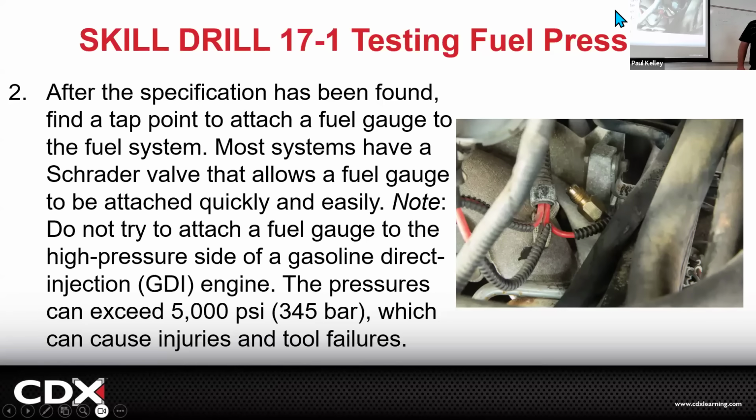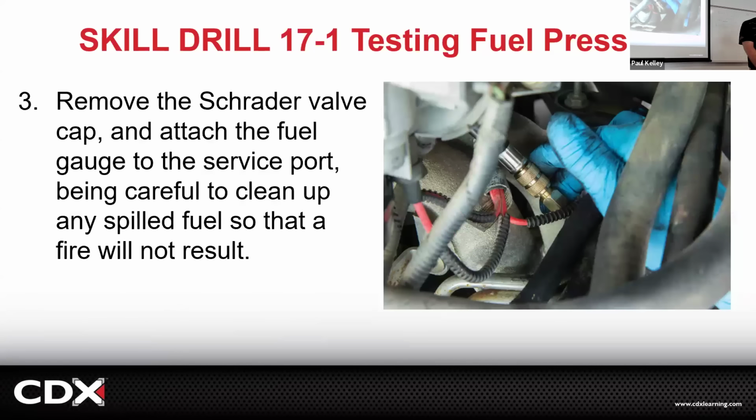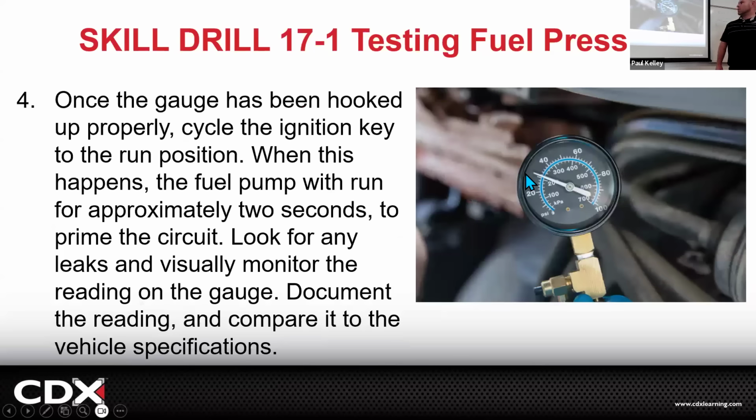Cool, so we just hook the gauge up and check the pressure just like it's a tire. So here we are, hooking up the gauge. It's easy, and then we're going to read it. What's this one read? Let's see, 20, 40. Well, first off, in here is kPa. Those are not freedom units. We want PSI. Those are freedom units. So 20, that number is going to be 30. That's 40. So we're at about 31 PSI.